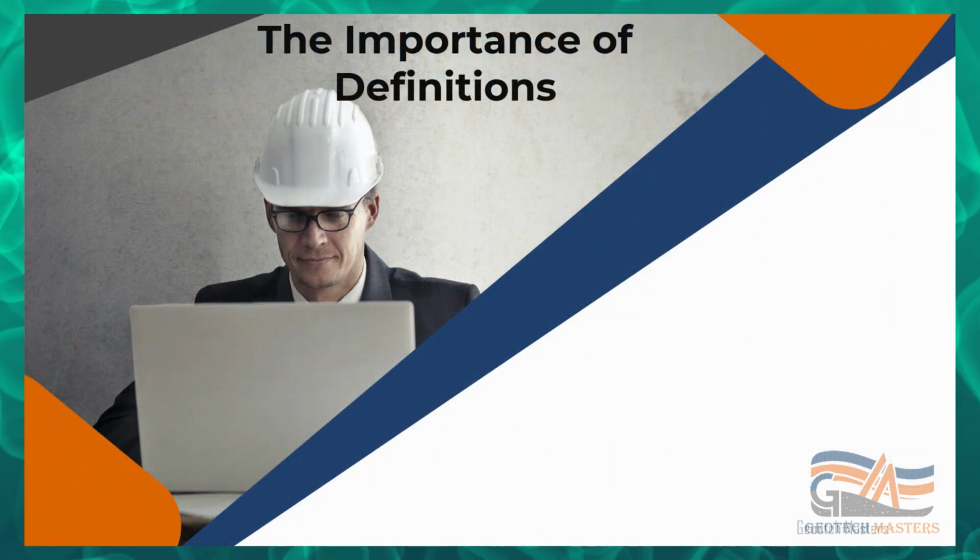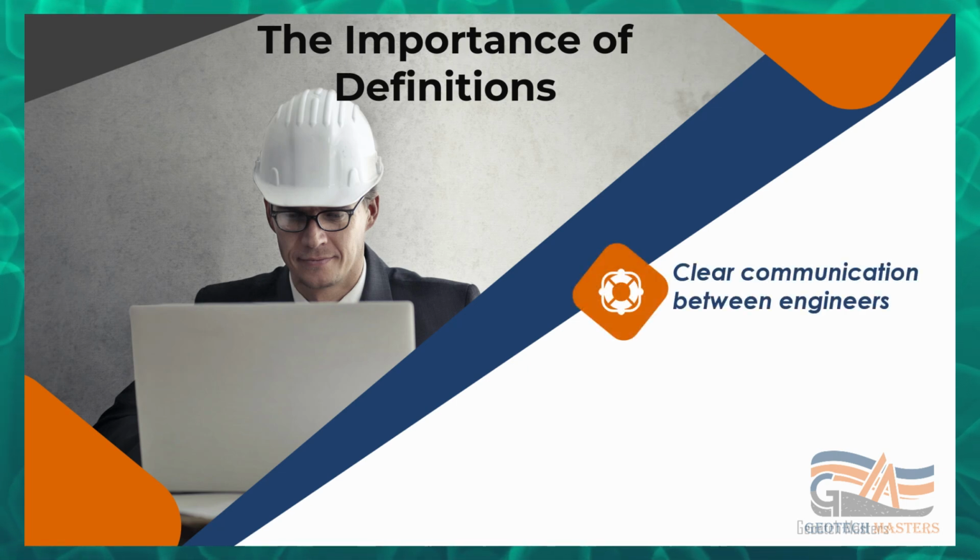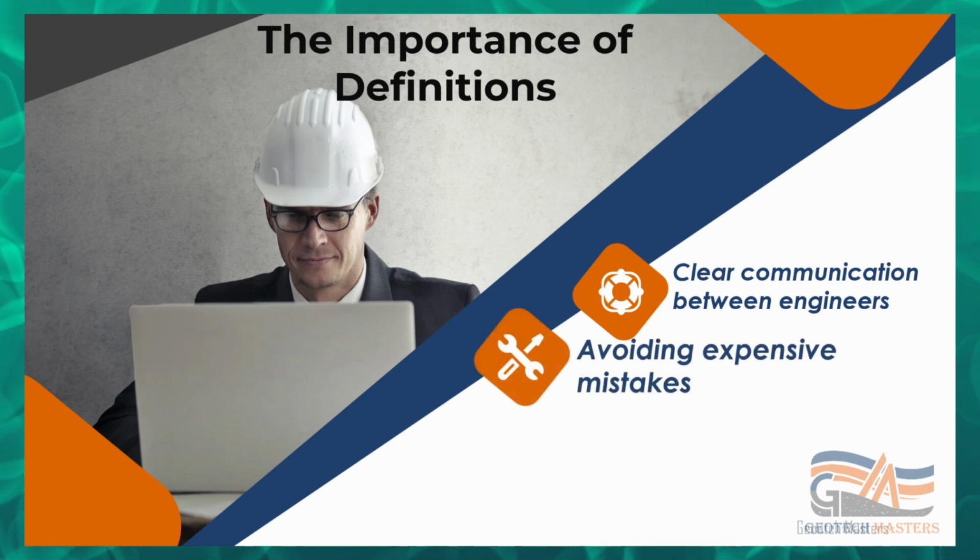Why do we spend time on these definitions? It is all about communication. When you write rock mass in a report, the design engineer needs to know exactly what you mean. Misunderstanding these terms can lead to expensive mistakes. If you design a foundation based on the strength of the rock material, but the rock mass is full of open joints, the foundation might fail.